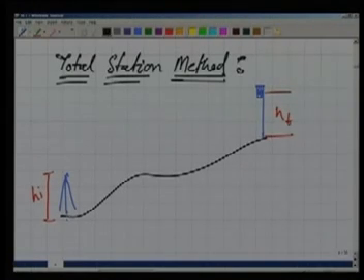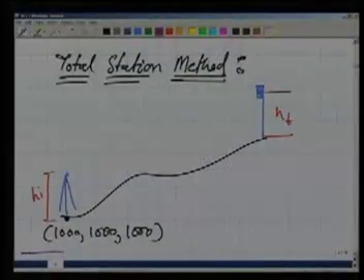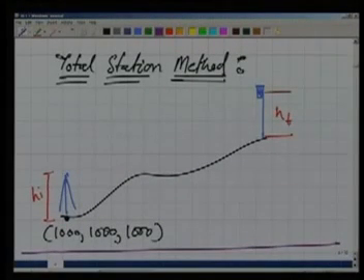Let us assume that for this point, as an initial point, its coordinates are 1000, 1000 and 1000, any arbitrary value. These coordinates could also be drawn from some existing reference system. Well, the datum in this case is, let us say, here, so this height is 1000.